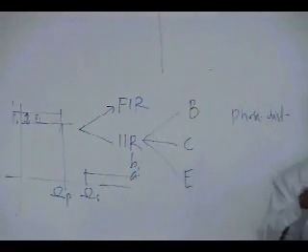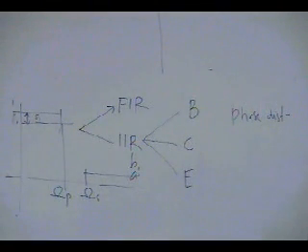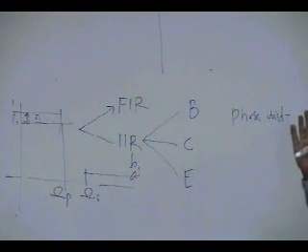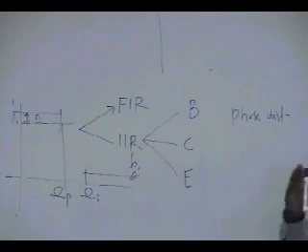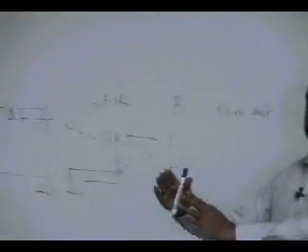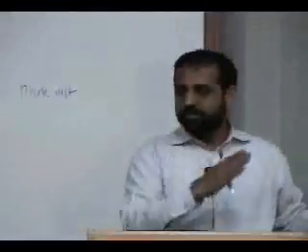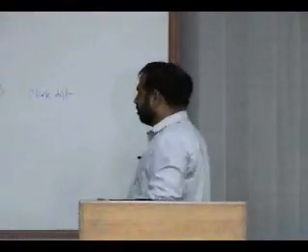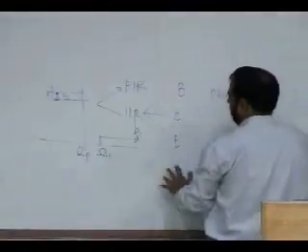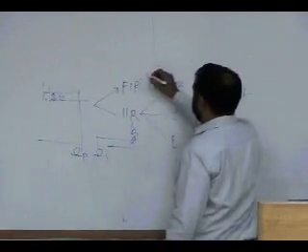Then you have B's and A's, and this is fine, but then you have to check the stability. How do you check the stability? You need to compute all the poles of the system, and then check whether all the poles are inside the unit circle or not. That will be done dynamically, in real time. So you get data, you design a filter, you check stability, and then you implement. With the next buffer, you again do the same thing. So we will be doing that. And then obviously you can do an FIR.